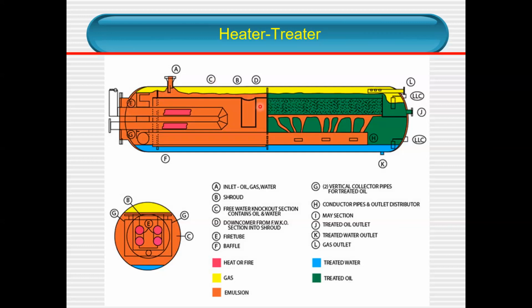If there is still any emulsified fluid even after the heater treater, you introduce chemicals. You introduce a small amount of chemicals, but without the heater treater, you might need a big amount of chemicals. So whichever is economical, whether you go through the heater treater, or both heater treater and chemicals, is the one with optimum cost.